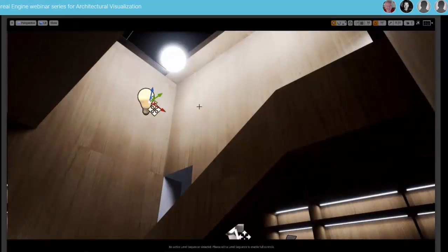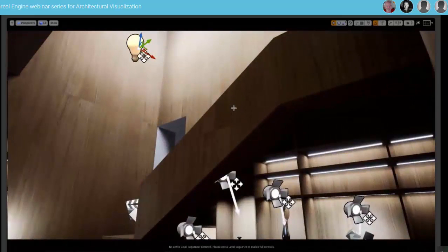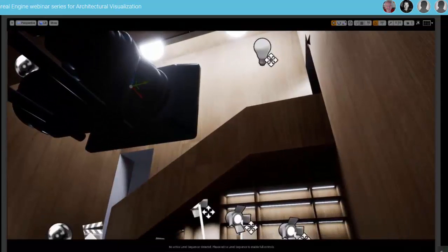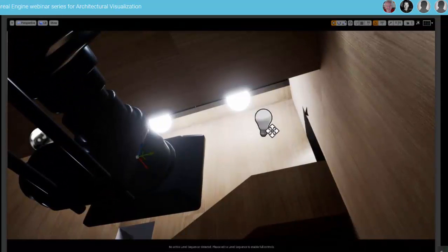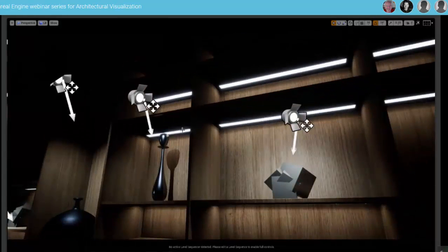And I've got Omnis here, but actually I've turned them off, so I didn't use them. I just put them in as a test and chose not to use them in the end. So the light in the staircase is only given by these two self-illuminating spheres, area lights, I call them. And the same thing, the back of these shelves are illuminated by these strips of white light.